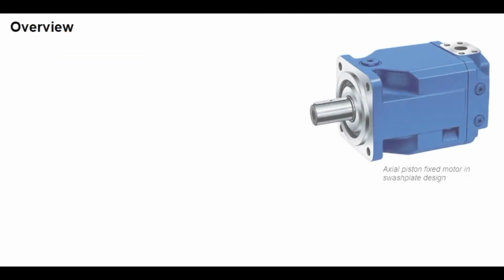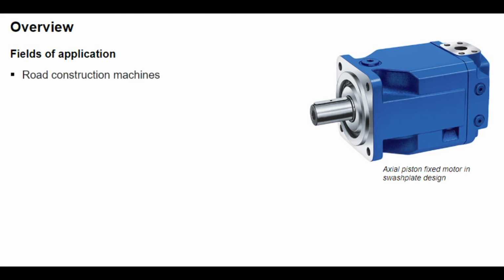The Rexroth A4FM motor is a swash plate axial piston fixed motor. It is used in open-circuit and closed-circuit hydrostatic drives for mobile and stationary applications, especially in tight spaces. It is primarily used in road construction machines, deep vibrators, mining, and offshore. The circuit symbol for this kind of motor is the symbol for a reversible fixed motor with a drain port